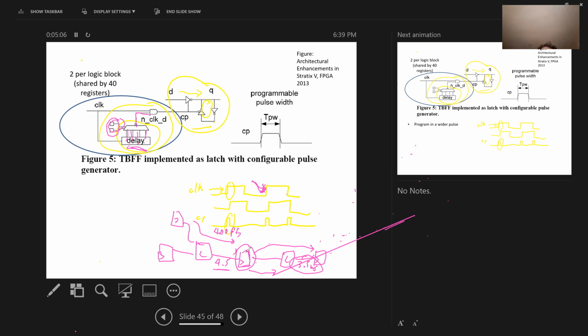Because the clock arrives, this data changes, and it can make it through this pulse latch in that 500 picosecond window where it's accepting new data and make it to the downstream logic. And that's a hold time violation, right? That basically means my data made it through 2 stages of pipelining in 1 clock cycle, which is never allowed.